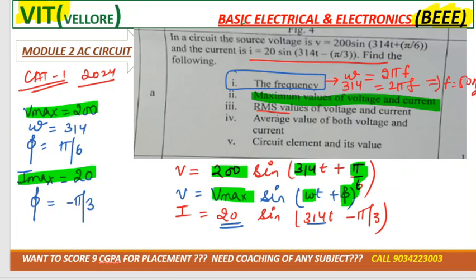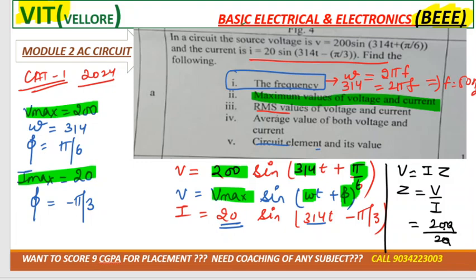Now in the next part they ask you the circuit element, whether it's a combination of R, L and C. See how can we get it? As you know, V is equal to IZ. So Z is V over I. V is how much? 200. I is how much? 20.